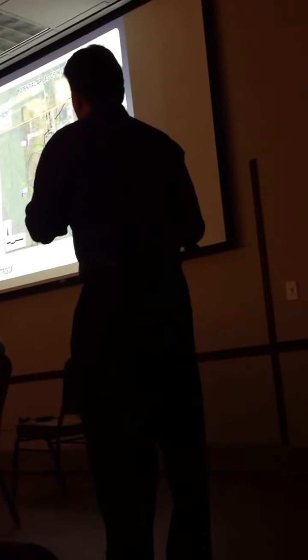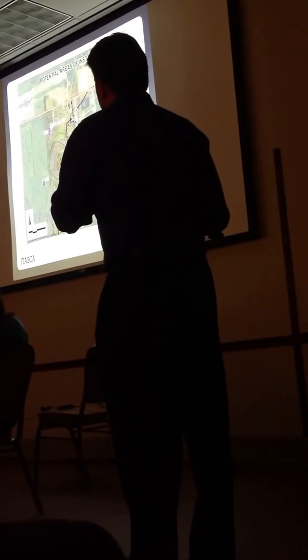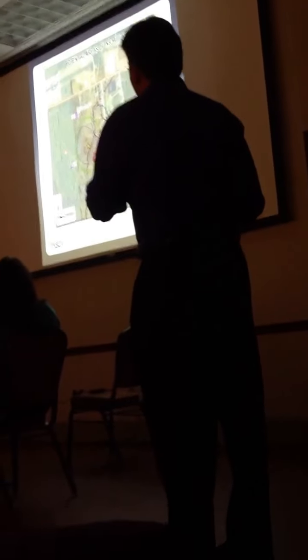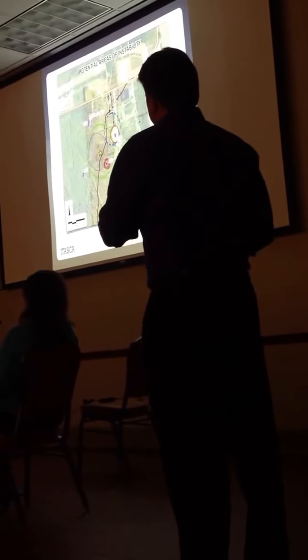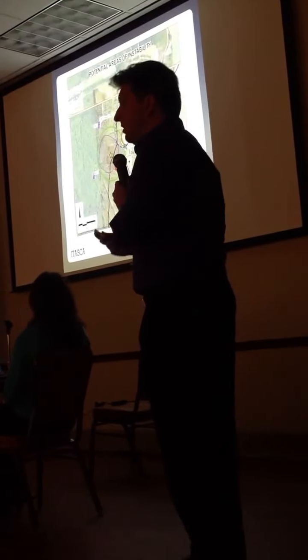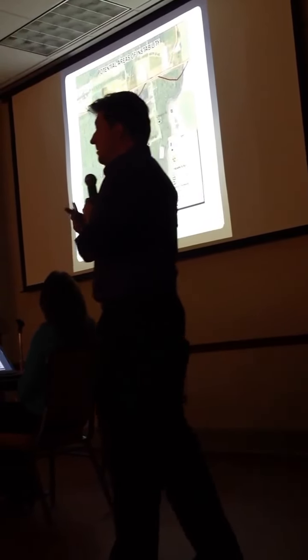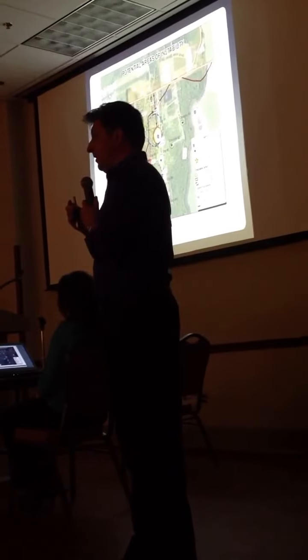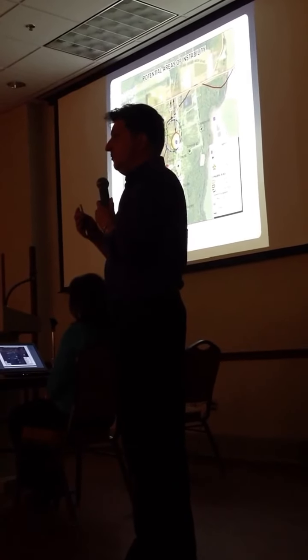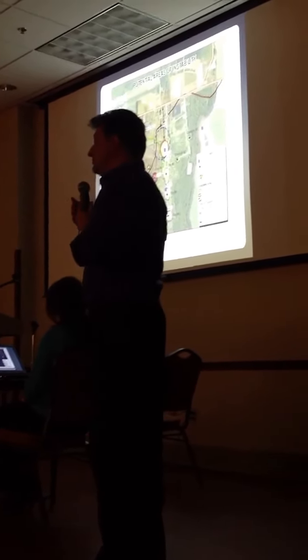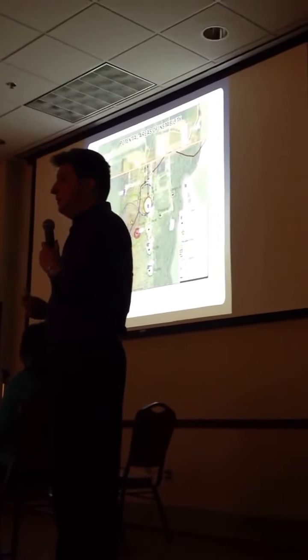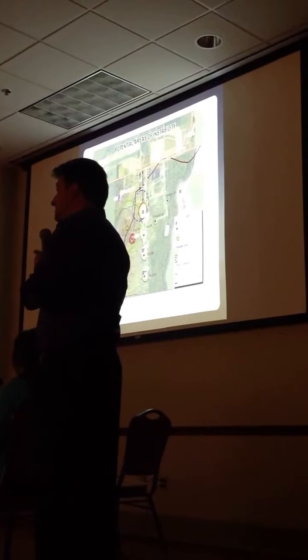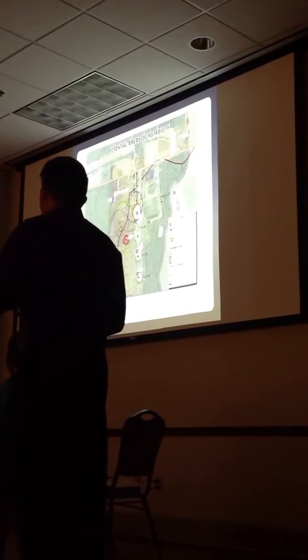We have another new well that's being instrumented very shortly up here, where another two sensors are going to go in. And we're also installing a microseismic system which is going to produce much more sensitive information with much better location accuracy. We're going to be able to see events with depth much more accurately, and that's really key. We're going to be able to see events accurately around the caverns.